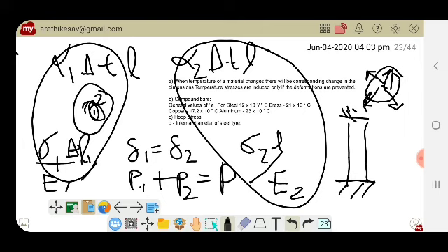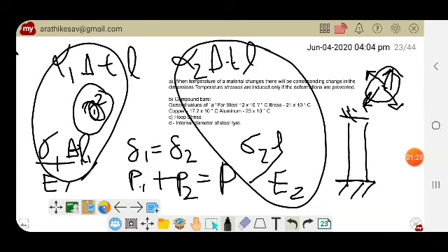And the internal diameter of a steel tire, what they mean is the conventional practice of fitting tires by heating. By heating, an expansion in the diameter happens, taking advantage of which we can insert the tire, and after cooling, it will remain tight. So that is the principle they are hinting at here.